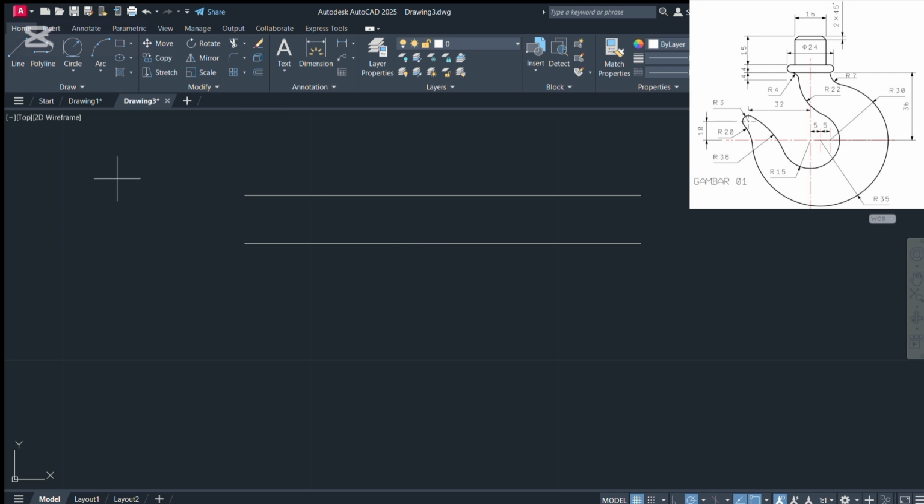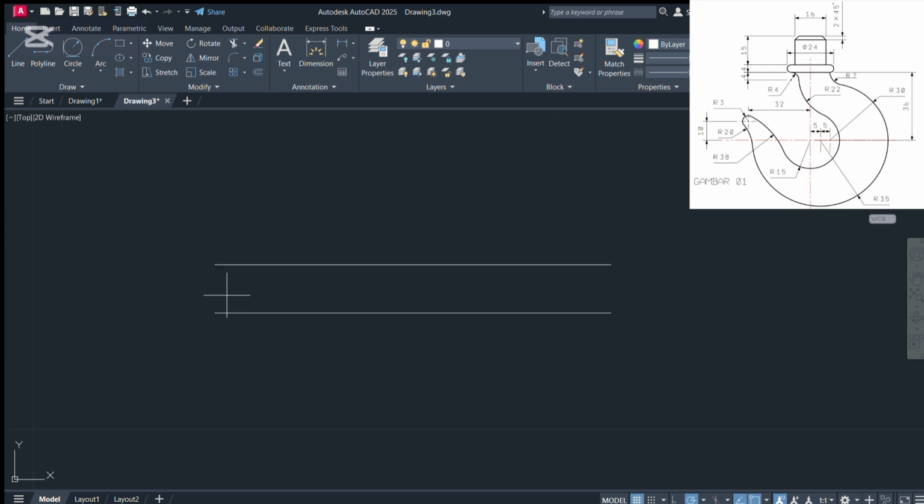From thereafter, you're going to enter the line command by typing in line or clicking on the line option in the menu. Then you're going to draw a line adjacent to the 90 degree by clicking on the tab button, then entering the degrees 45 degrees. Then a line should appear like the one you're seeing on the screen. Then you click on mirror once you've selected the line and click on the midpoint of that line. Another line will appear on the opposite side.